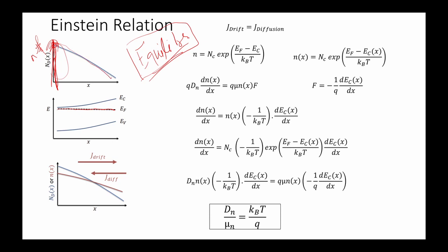As the concentration decreases, the conduction band moves farther from the Fermi level, because the Fermi level should be constant, as there is no flow of current. The conduction band and valence band should follow, because we are not changing the band gap. The band gap remains constant.